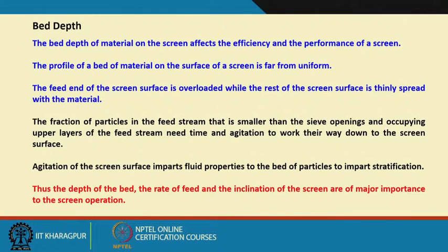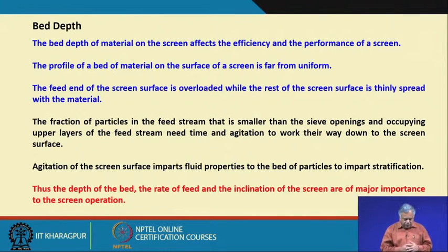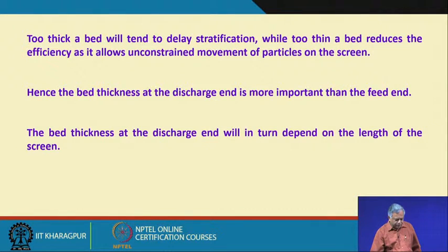This thing we will discuss more, that is fluidization, when we discuss a separator called the jigging operation. So, the depth of the bed, the feed rate and the inclination of the screen are of major importance to the screen operation.